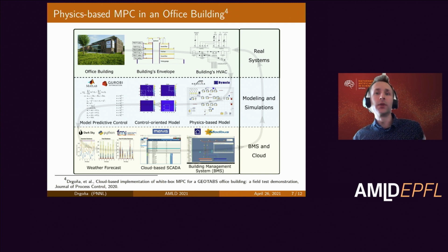And then in the modeling and simulation steps, we design these high fidelity digital twins, basically. People use domain specific languages like EnergyPlus or TRNSYS. We use Modelica in this case. Then we obtain this control oriented model for design of the model predictive controller, and only then we apply this strategy in real time. And after this, we still need to do some manual tuning based on the performance in the real world. Basically, this design, modeling, tuning, calibration took us several months to have this field test deployment.